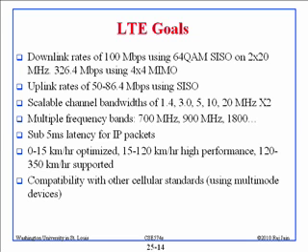Okay, so what could be SISO? Right, single antenna. So, scalable channel bandwidth. That's another thing: previously the channel widths were fixed. So if you had WCDMA, you had 5 megahertz, you couldn't have 3 megahertz, you couldn't have 7 megahertz. Right? Now they are going to use whatever they can get from 1.4 to 3 to 5 to 10 to 20. But you need times 2. And you can actually do times 1 too because it does TDD as well.